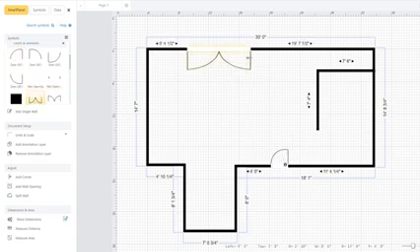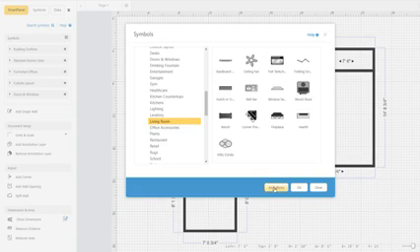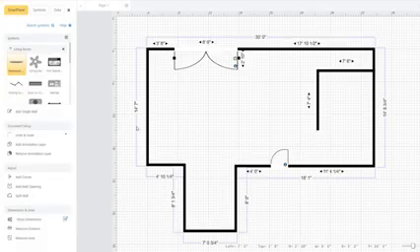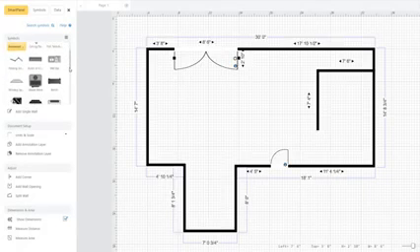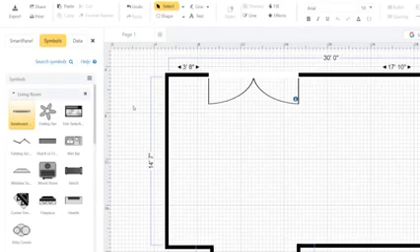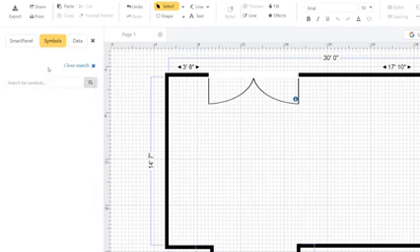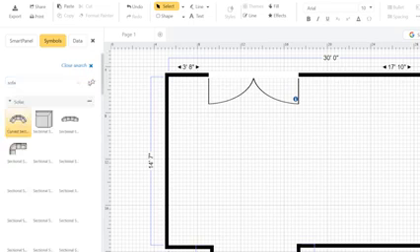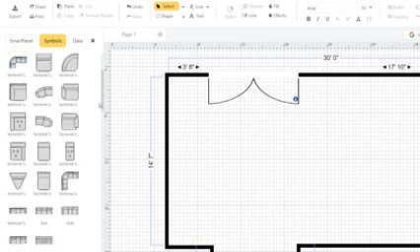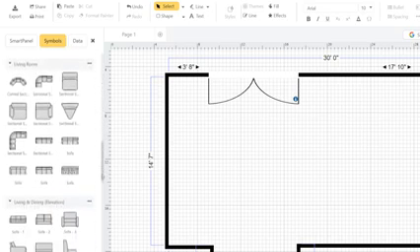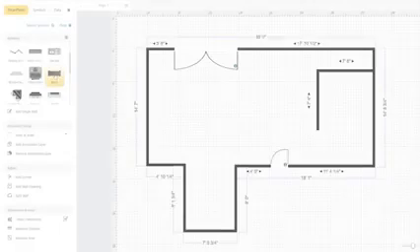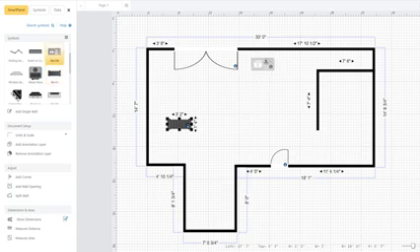From a vast array of libraries, you can easily add furnishings, appliances, and hundreds of other symbols. To search for any symbols that aren't already in your library, click on the blue Search Symbols text at the top of the Smart panel to open the Symbols tab with a search bar. Type any keyword and hit Enter, or click here to search. The search results will be grouped by the libraries they were found in. Just drag and drop them to where you want them to go in the room.